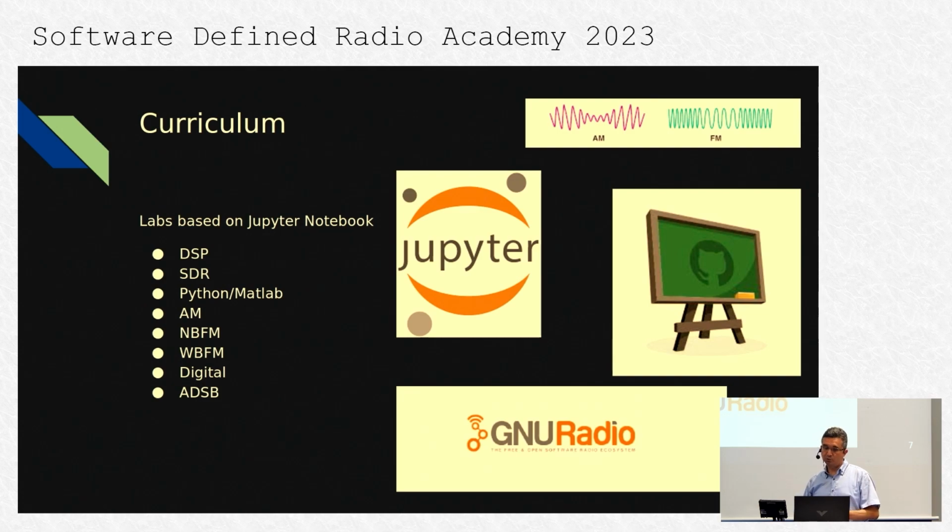The notebooks include records of real-world signals. Students also apply their algorithms to live signals they have taken themselves. And in classes, I also transmit using HackRF, so they have the opportunity to catch signals that have a low chance of being found on the air. Students record them and then complete their assigned tasks. GNU Radio is used all throughout the course, both for signal analysis and for offline and real-time demodulation.